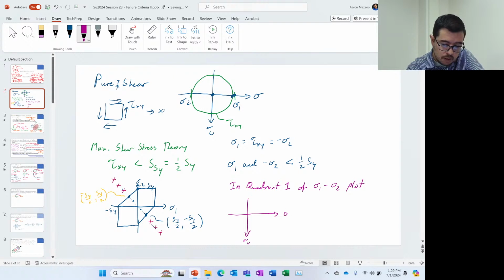So that's tau, this is sigma, and I have a sigma 1 out here, and sigma 2 could be anything. Let's just say sigma 2 is right there, arbitrarily. If we assume that sigma 3 out of plane is at the origin, then the maximum shear stress is going to be, well, you tell me, what is the maximum shear stress?